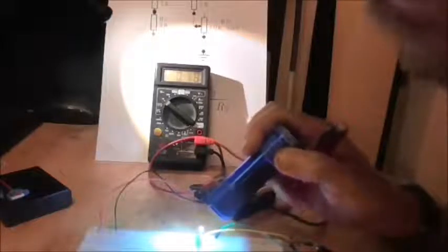Take it away again, slowly, and if you can see the multimeter there quite clearly, you'll see that the further away I take this light, the more the multimeter goes up, and the more output voltage we're getting from the node of the voltage divider. And there we are. What we've actually made there is a dark activated sensor. Goes dark, puts out more voltage.